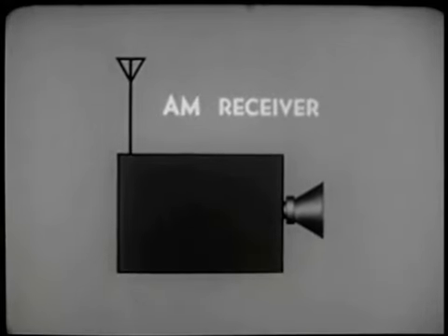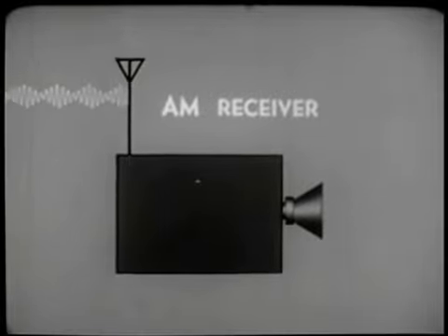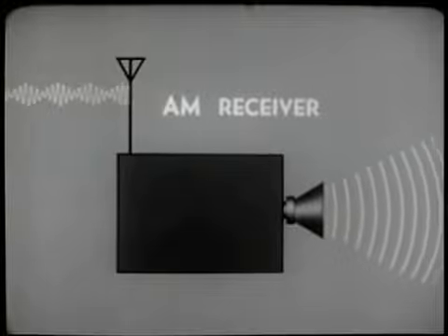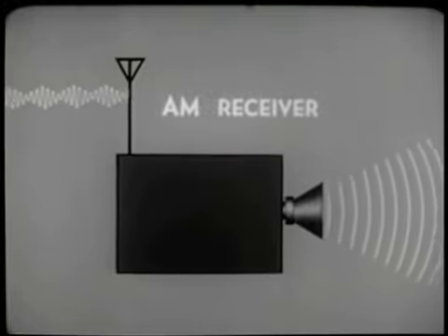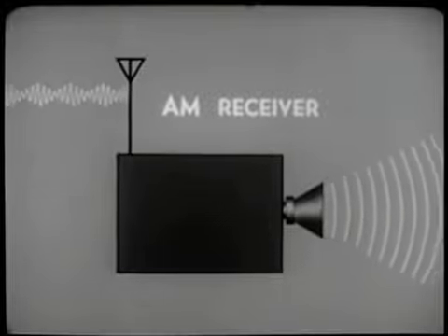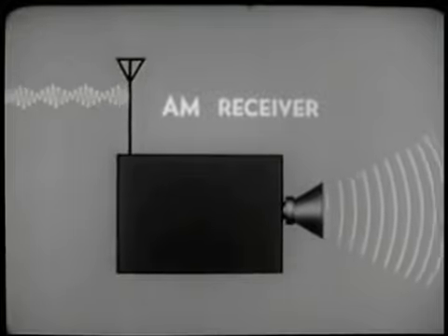The receiving antenna will pick up both the composite RF waves from the transmitting antenna and the random noises generated by the lightning. These two will combine and distort the amplitude of our desired signal. Now a partial review of what happens in the AM receiver. The amplitude modulated RF carrier is picked up by the receiver's antenna. The receiver extracts the intelligence carried by the RF, transforms it back to an audio signal, amplifies it, and feeds it to the speaker. It emerges from the speaker as sound waves, which can be heard and understood by the human ear, unless the intelligence is smothered by interference.